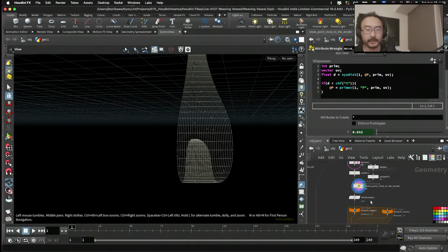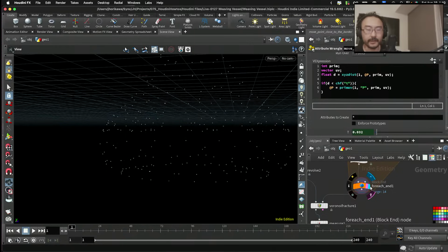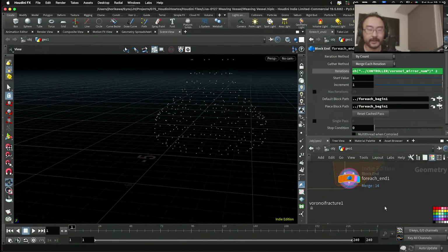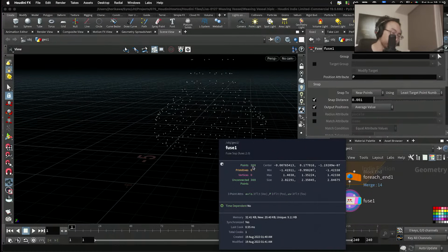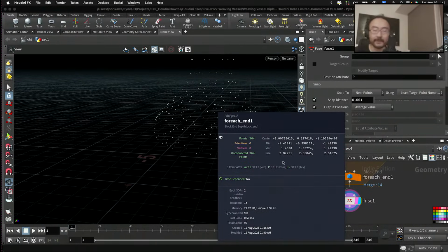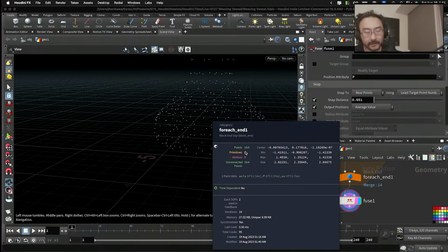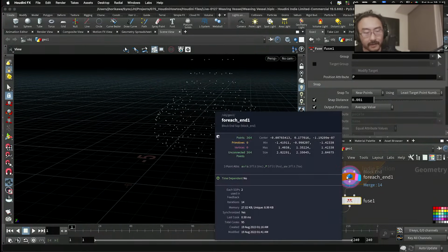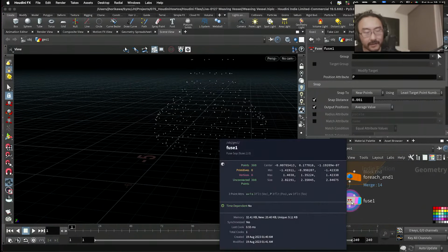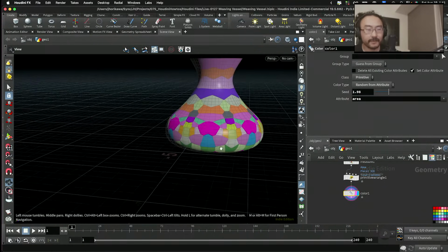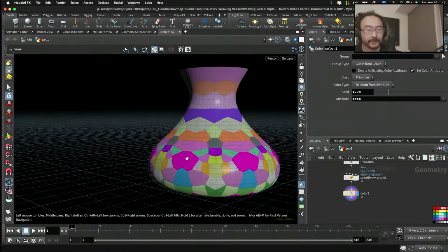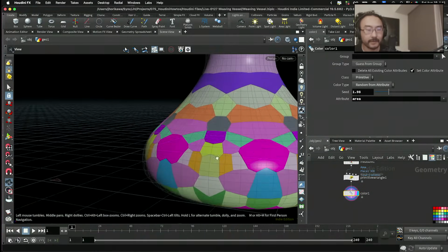Alright, now going back to the final output here, I can then use the fuse node. So if the point is at the duplicated point position, then it will be trimmed to a single point. So previously it was 364 points. After the fuse, it's the same. No, it's after the trimming, it's 308 points. Okay, so as for the final result, you're going to get a better result.